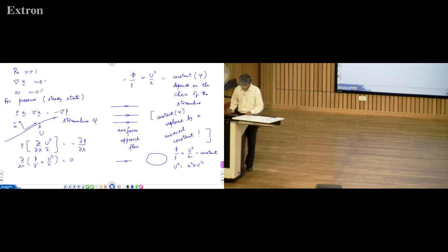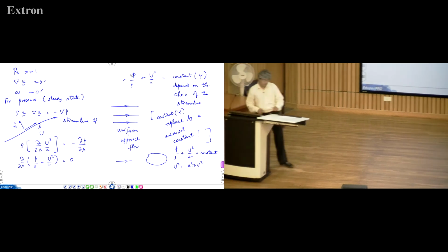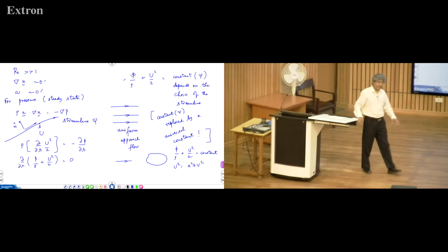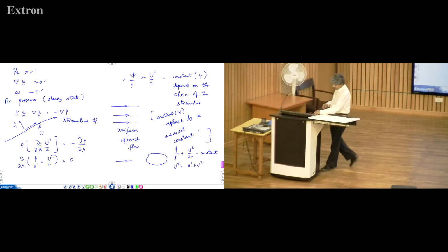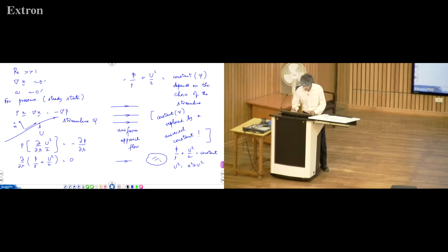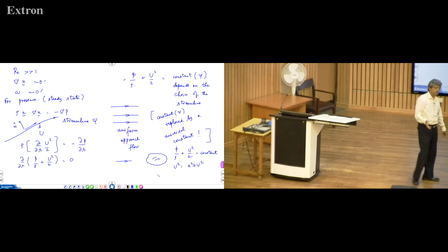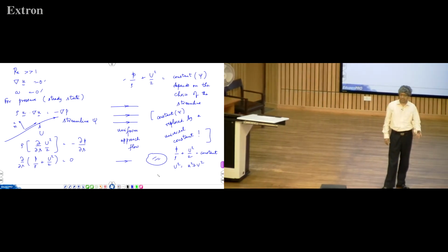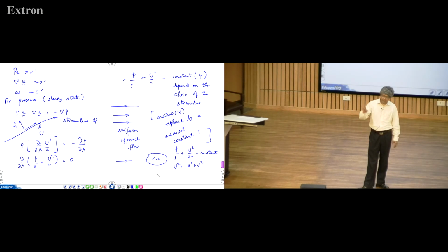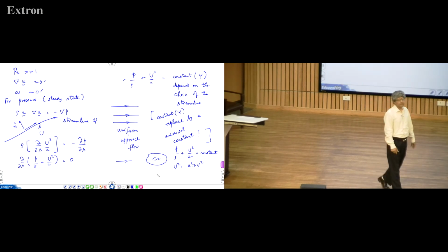Okay. So, of course, once you get pressure, you have to integrate pressure on the surface of the object suitably to get forces acting on it. That will give you all the forces. Why? Because the viscous part, the shear stresses are 0 in the limit of Re approaching infinity.